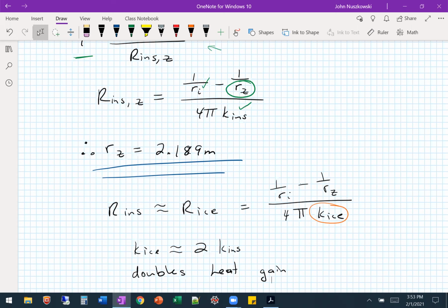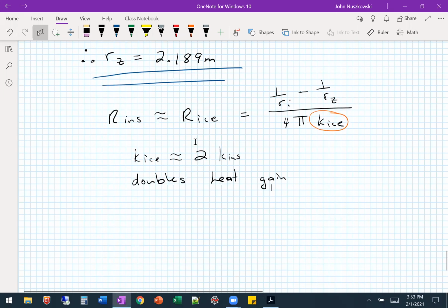So how could this situation be avoided, right? That's where we don't want this water to keep making its way there to build up that ice, and that's basically done with a vapor barrier. It's just a surface that doesn't allow water to transfer through. So put that on the outside of your insulation. Any questions?